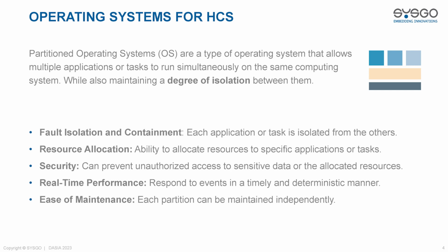Maintenance, meaning that updates or changes can be made to one partition without affecting the others. This can simplify the maintenance and reduce downtime, which is important in space computing systems where downtime can have serious consequences. All these characteristics are key to allow the consolidation of multiple applications having different levels of criticality, either for the functional safety or the security of the onboard equipment, and ensure the required real time.